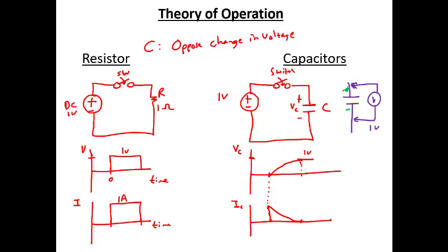So what you need to do is let these electrons that are stored on this negative plate get back to the positive side to discharge. Now you can discharge them by putting a resistor across here. So how long this takes to discharge the capacitor will be related to the resistance times the capacitance. And in the lab, sometimes what we do is we'll charge up the capacitor and then we'll put our voltmeter across the capacitor. A voltmeter has approximately 10 mega ohms of resistance, and you can actually see the voltage on the capacitor discharge on the multimeter.